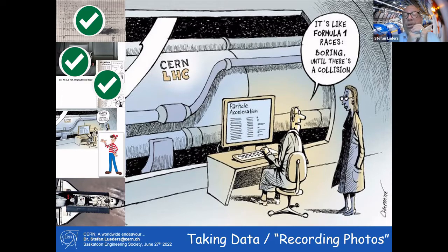The magnets themselves, we're monitoring the temperature of the magnet. So if the temperature is changing just a little bit, if we see that it's coming close to the safety envelope, then we got machinery in place, which we call the beam dump. Remember what I said at the beginning, we dump the beam. You can do this by operator intervention, but you can also do this automatically by one of the safety systems triggering. And this costs us about 4 microseconds or 4 turns in the accelerator. So 4 turns we need to get rid of the beam. And once the beam is gone, we have a very, very safe situation.